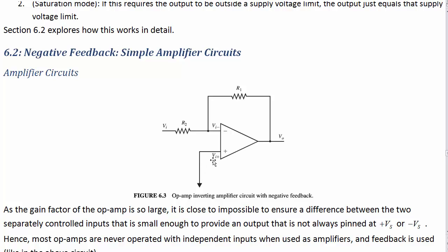So we can magically set this input to be at 0 voltage through hooking up the other one to ground and having this feedback, and also pull current through there, but then direct it somewhere else through the magic of an op-amp. So the current goes through here, through a voltage of V1 over R2, and then ends up being forced up this way.